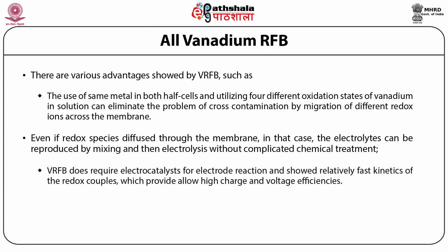Second, VRFB does not require electrocatalyst for electrode reaction and showed relatively fast kinetics of the redox couples which allow high charge and voltage efficiencies. The overall energy efficiency of about 70 to 90% has been observed with a 1 kilowatt VRFB stack.